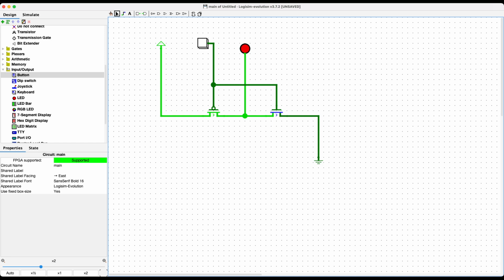So whatever the voltage is, let's say 5 volts is our operating voltage. High voltage would be something in the range of 4.7 and above, so basically close to 5. Low voltage, which will count as a 0, would be stuff close to, it may not be exactly 0 volts, but way down there. The stuff in the middle is sort of the no man's land that we hope we're never actually in, because that's weird. But if we design things right so that we're basically always in a state of either high voltage or low voltage, then we've made a digital thing: ones and zeros.